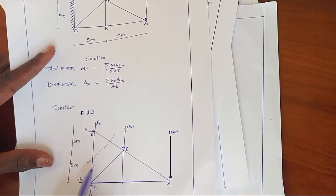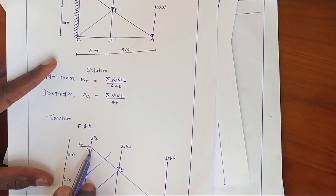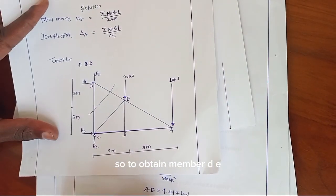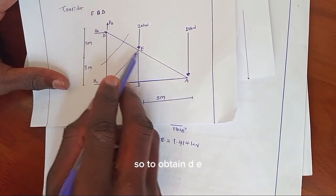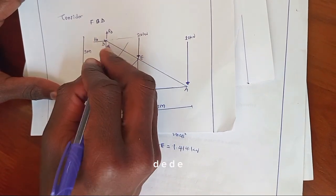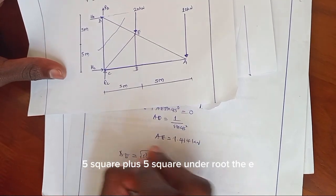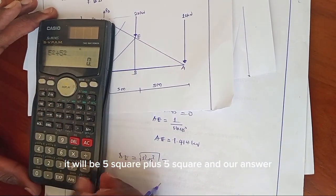This is the length for member AE. To obtain the length for member AE, to obtain the member DE, we may proceed in this way. To obtain member DE, we use Pythagoras theorem. DE is this one, so it will be 5 square plus 5 square under root.